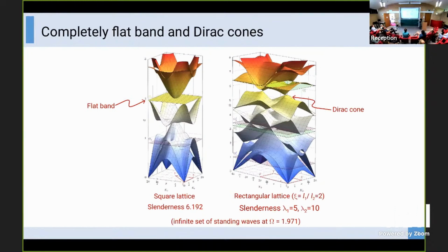I guess you do higher frequency homogenization. What I do is use low frequency, long wavelength to obtain the effective continuum. This disappears in that usage. You get higher order stuff if you do higher frequency homogenization, but I never think the classical one does higher frequency homogenization. You never get a flat band.